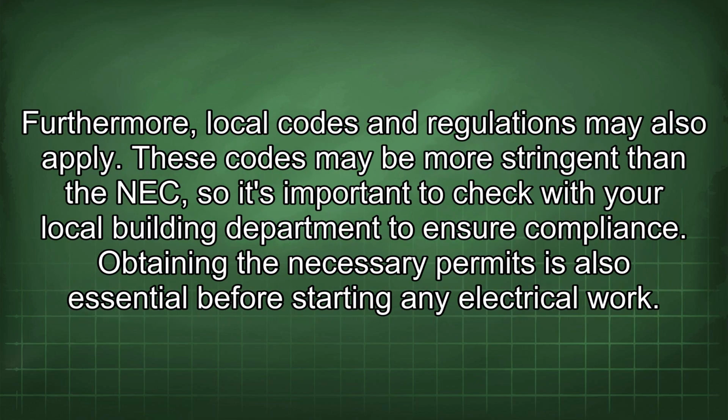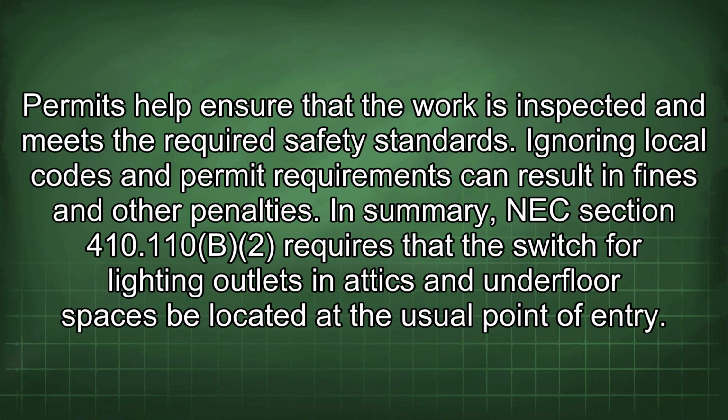Furthermore, local codes and regulations may also apply. These codes may be more stringent than the NEC, so it's important to check with your local building department to ensure compliance. Obtaining the necessary permits is also essential before starting any electrical work. Permits help ensure that the work is inspected and meets the required safety standards. Ignoring local codes and permit requirements can result in fines and other penalties.